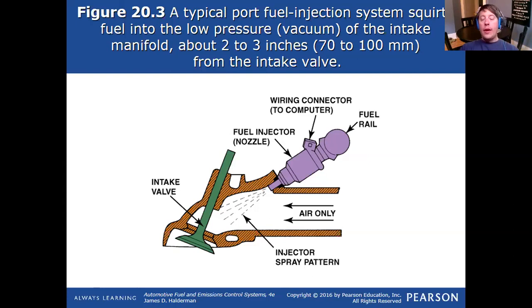If you get into high performance building, those of you that want to build race cars or something, you get into tuning software, this becomes a very big deal. Because if you change out fuel injectors, you have to tell the computer what fuel injector it has. And if you change manifold vacuum with a camshaft, or you change to an aftermarket fuel pump that's at a different pressure, things get crazy in a hurry.